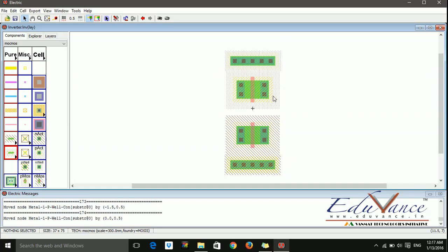Okay, now with this done, let us make the connections. First click on the polysilicon and click on the other one. The connection is made. Now you can see a straight line coming since the entire inverter is aligned. Now suppose the inverter wasn't aligned, it was something like this, and you just made the connection. You can see a crooked line forming.